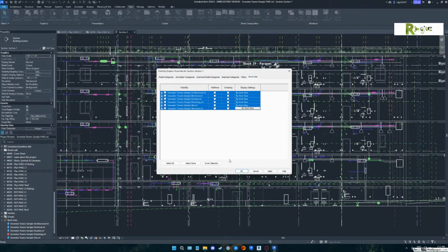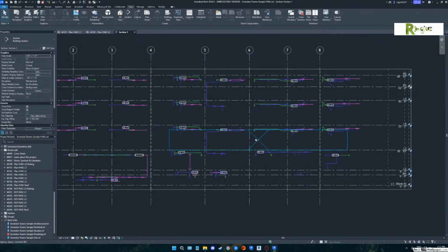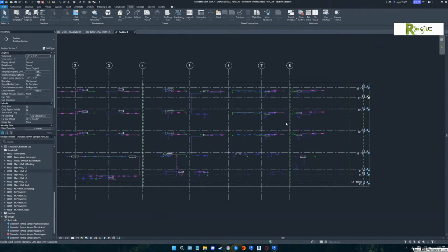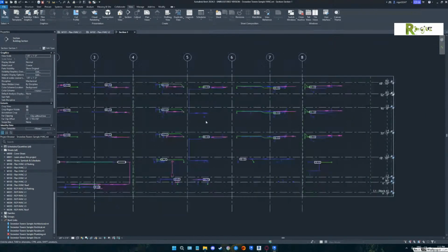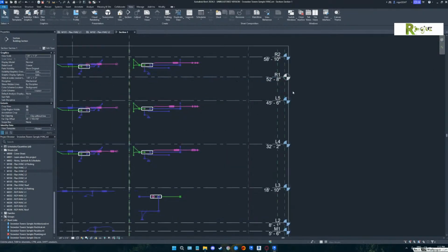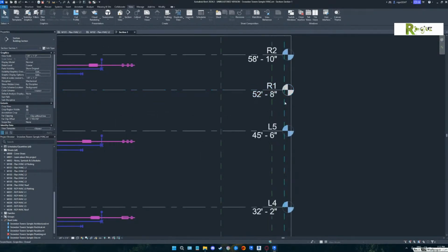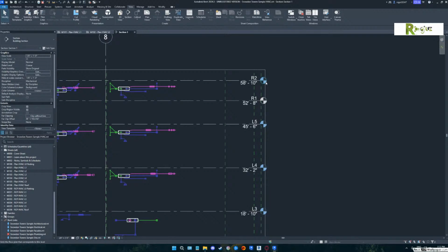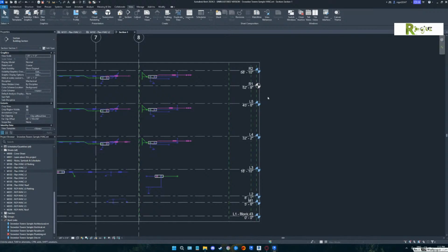Nice sample project. I don't know if you saw it, but there was one that wasn't even on. It wasn't even highlighted blue, so you couldn't go to it. What does that tell you? It's not on. There is no corresponding level to that line. Or if it is, it's a different name.